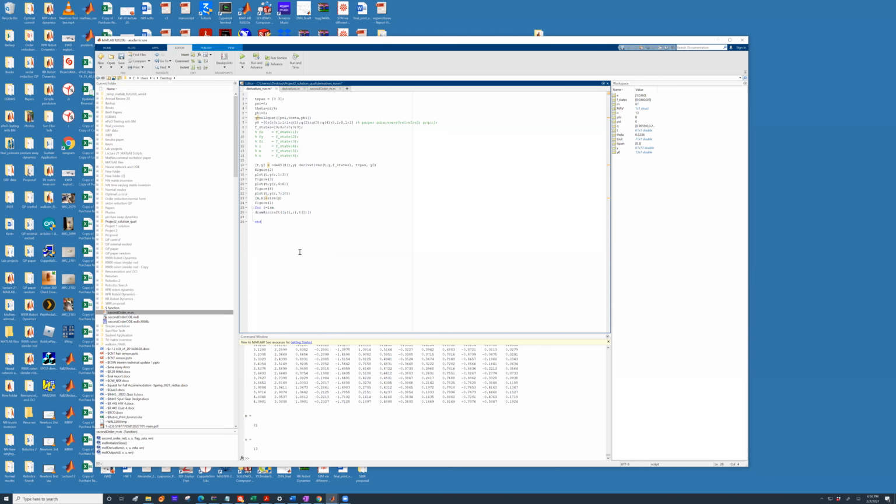And let me ask you this question, and you can answer in the chat window. If I run this code now, would it plot the aircraft? You can tell me before trying it. It won't. The reason for that is the values of the output, the Y values that we are trying to plot, they are in quaternions. And the values that this function is expecting, they are in Euler angles.